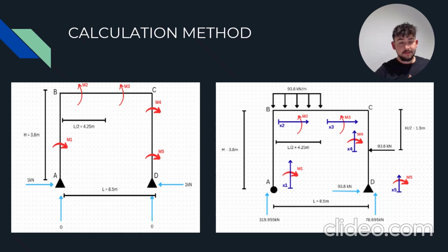As you can see in the left photo, I had to make the vertical forces 0 and made the horizontal forces 1, and again had to do 5 different cuts and find the 5 different equations to then be able to calculate the horizontal displacement of the primary structure at point A, and similarly I had to calculate the horizontal displacement of the virtual structure at point A as well. By doing this, I was able to get the final reaction forces at point A and point D.